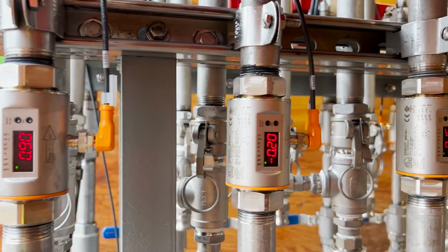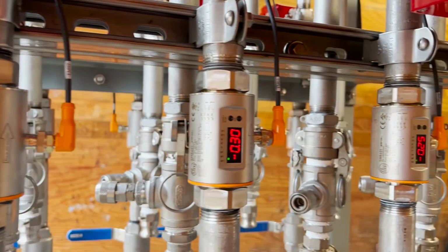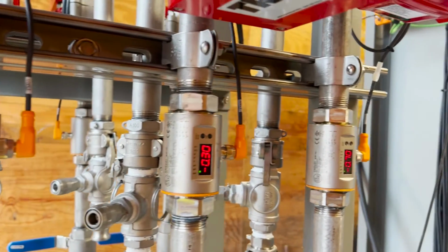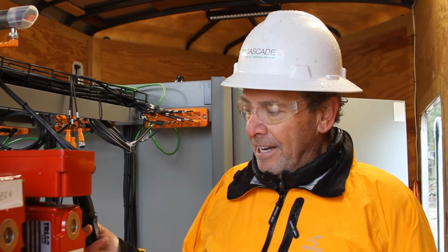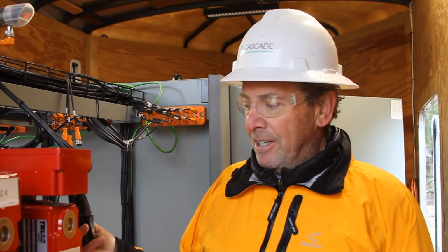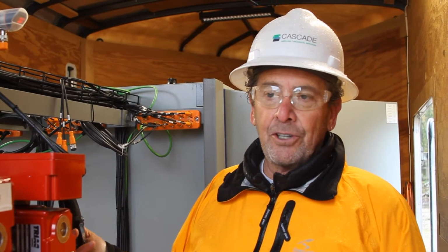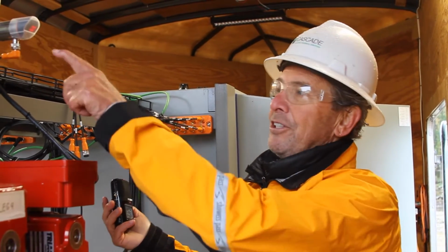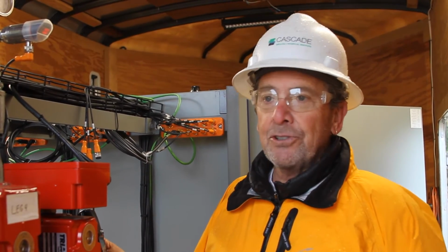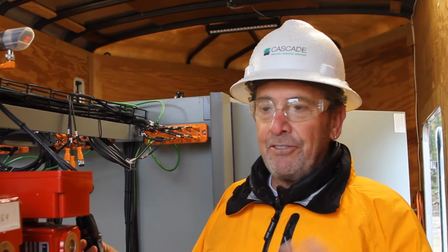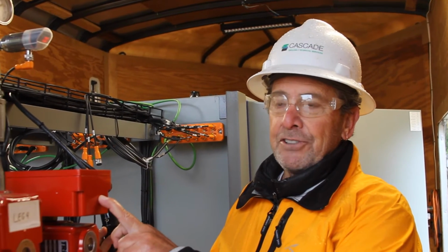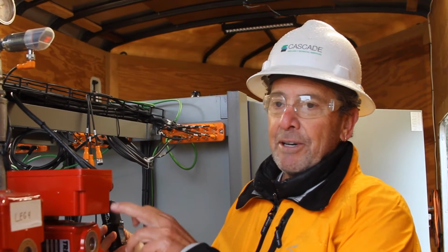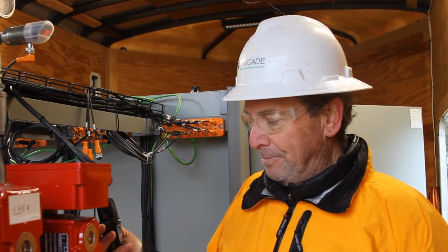These are really the most robust and accurate flow meters we have in the industry, and they also log all the data. They give us the ability to not only totalize the total injection flow, but also give us instantaneous flow measurements. So both the mag flow meters and the digital pressure transducers are the two really key monitoring components that feed our computer control system and eventually control these valves, either open them or close them, to make sure we stay within the design limitations.